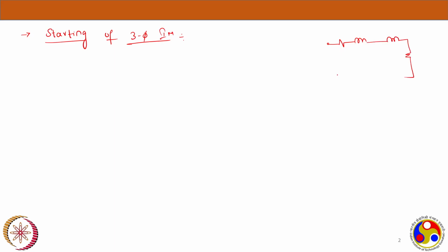So we have the stator side and rotor side, and if we neglect the magnetizing branch, as its magnitude is big enough, we already discussed the equivalent impedance will be of the lower order terms, which is R1 and X1. So I'm writing an approximate equivalent circuit just to understand the starting concept, with the slip.